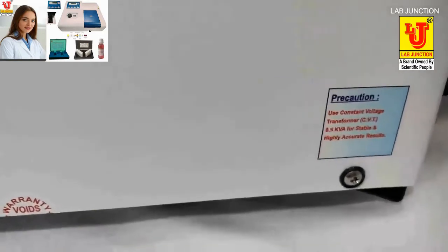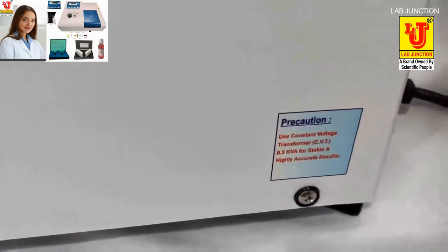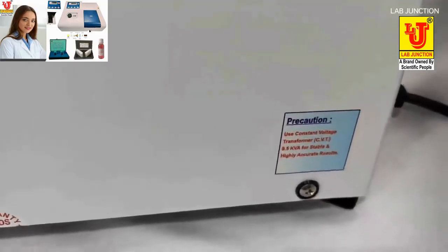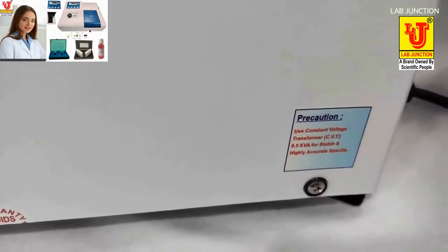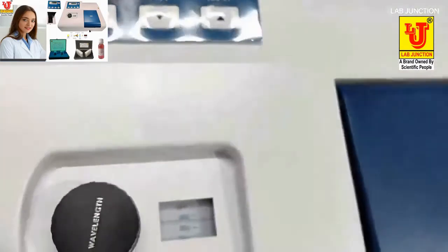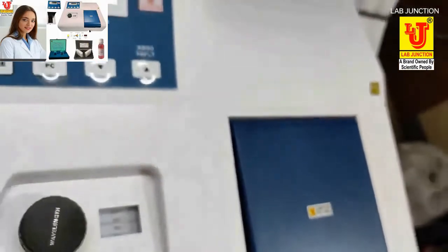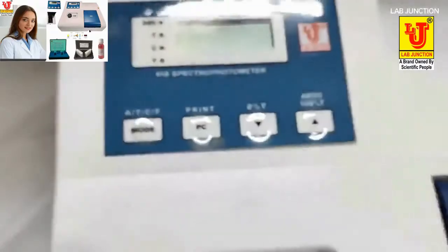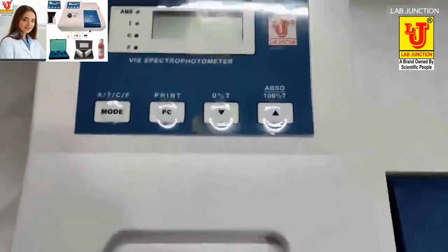A precaution is there. Precaution is always use 0.5 kVA stability for power. Always use a 0.5 kVA CVT stabilizer to protect the spectrophotometer.